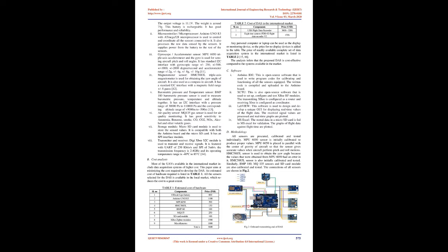The MPU 6050 triple-axis accelerometer and gyro sensor is used for the calculation of aircraft pitch, roll, and yaw angles, because it not only produces values with less noise but also has good dynamic response. 6. However, the sensor itself did not have a magnetometer in it. So, the yaw angle values were inaccurate. This problem was solved by using a 3-axis magnetometer. In this project, we have used the HMC 5883L as a triple-axis magnetometer.